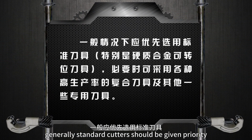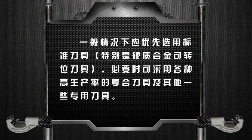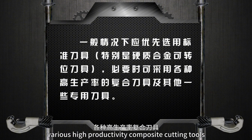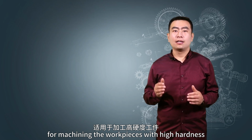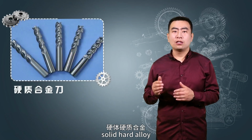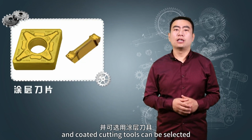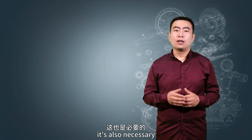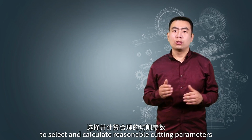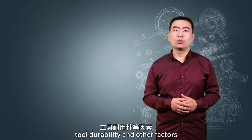Generally, standard cutters should be given priority, especially the hard alloy reversible cutting tools. When necessary, various high-productivity composite cutting tools and other specialized cutting tools can be used. For machining the workpieces with high hardness, solid hard alloy, ceramic cutting tools, and coated cutting tools can be selected. Then, knowing the types and materials, it's also necessary to select and calculate reasonable cutting parameters based on machining accuracy, tool durability, and other factors.